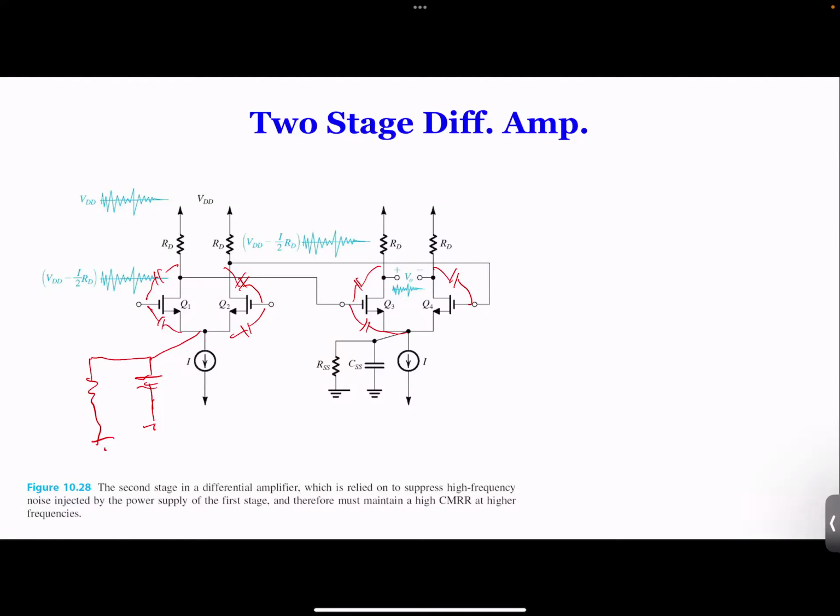So those noises coming in, the voltage, it is picked up by this. Because VDD has a noise. Even if RD has no noise, I has no noise, but this VDD minus this one, the noise is coming here because VDD has a noise. And that noise is on top of the DC, very small, typically in the millivolts. Your voltage is say 5 volts, 10 volts, 12 volts, whatever, right? Your noise is in the millivolts.